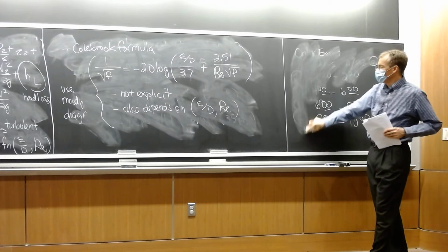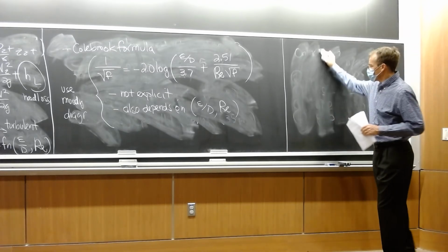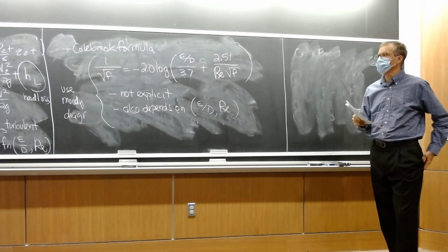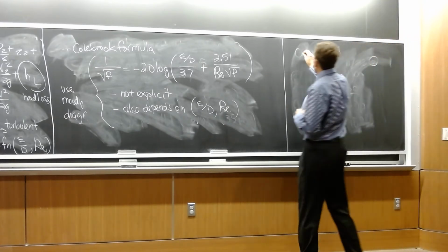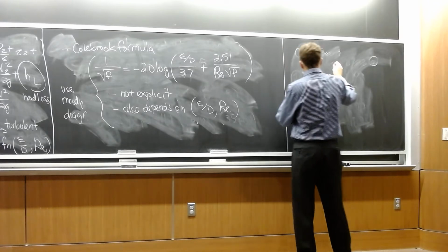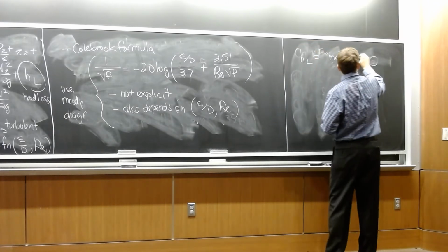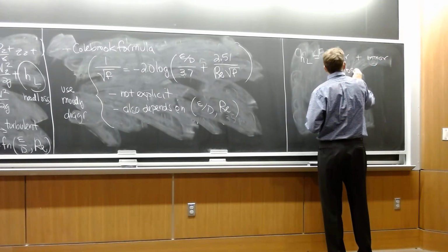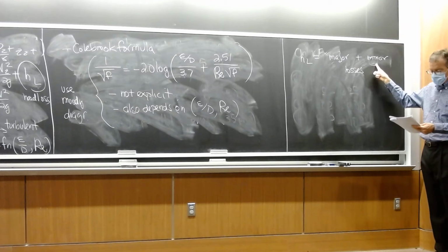But even if you can do that and come up with the friction factor, it turns out that there's more than just those sorts of head losses that we have to worry about. There's another part of this, minor losses.